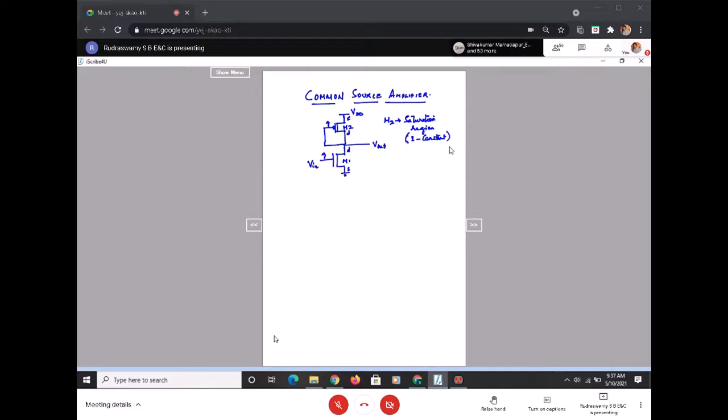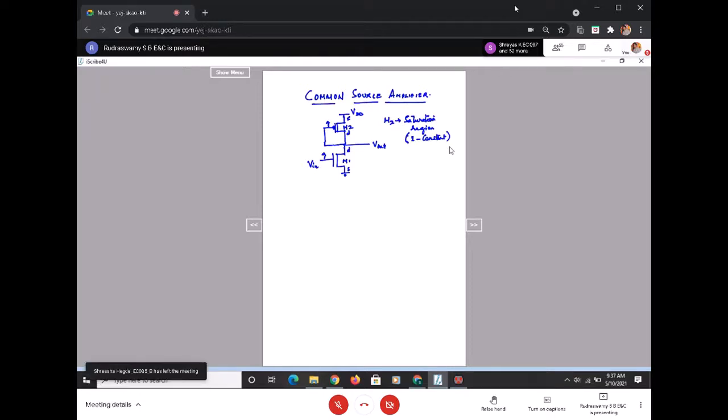And this is what we had said. If we add a resistance of some 100 ohm, VDD is fixed and the resistance is fixed, which means a constant current flows. In a similar fashion, we are replacing a resistance, which is a passive component, with an active device, the two terminal diode kind of connection of this transistor, ensuring it operates in the saturation region, making sure my current is constant. So this is now acting as a constant current source. Typically it is now acting as a load.